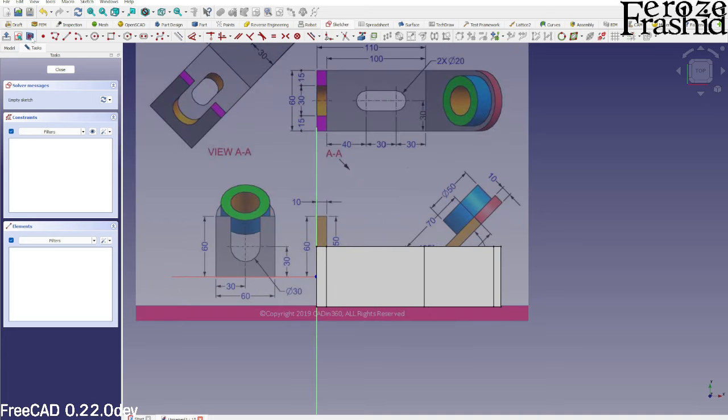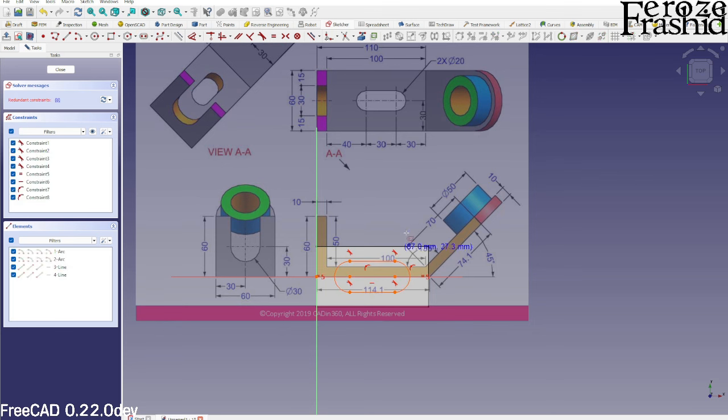And here turn on the section view, and so this is the center. Don't worry about this drawing on the back, we are looking at this. So it would be a slot, and we have 1 degree of freedom additional, so let's delete that. Now this radius is 10, right?